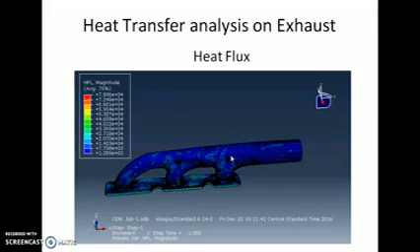To define properties of the outer surface, a boundary film condition is selected and the outer surface is selected. The base and face of this hollow pipe are selected to be fixed. But one thing to remember in heat transfer analysis is that we always have to give the Stefan-Boltzmann constant and the absolute temperature in Kelvin.